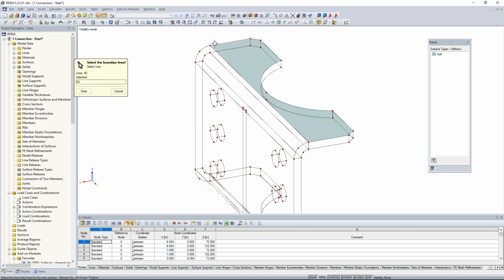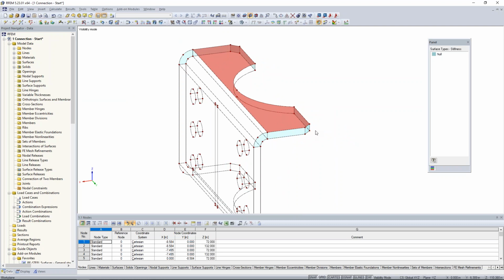Now, the exact same thing needs to be done for all of these smaller surfaces around the edge. So I'm just going to, again, move around in the circular direction. I'm going to skip this curved surface. And we know the reason why, because this is not in a single plane. So my element that I am utilizing right now only allows me to define these surfaces in a single plane. And we'll actually utilize these curved surfaces here on the side because these are in a single plane still, and we are done.